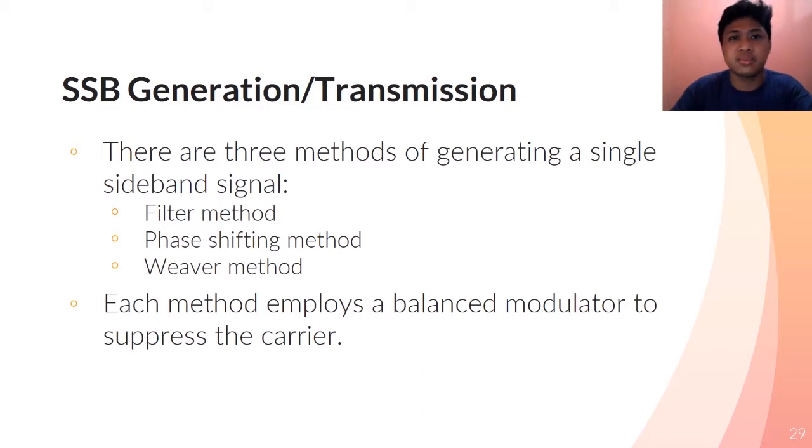The circuit where the carrier is reinserted is called a linear summer if it is a resistive network, and a hybrid coil if the single sideband waveform and the pilot carrier are inductively combined in a transformer bridge circuit.